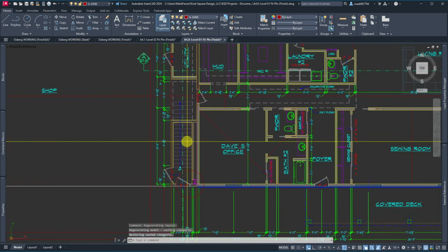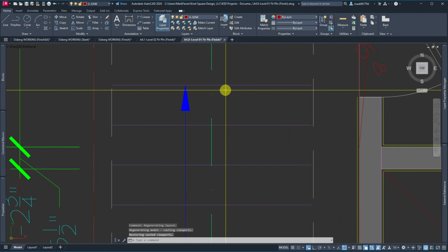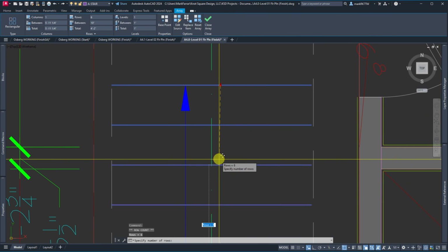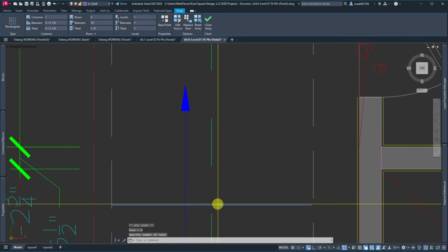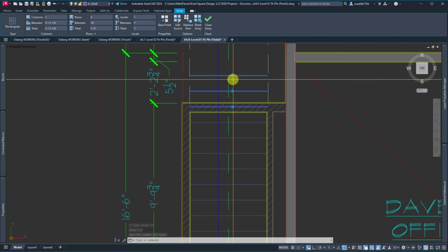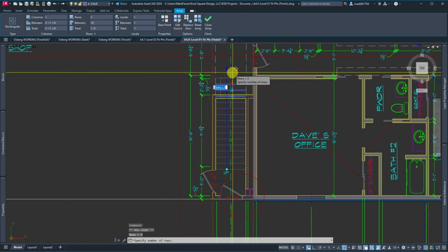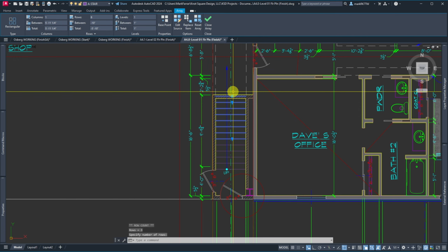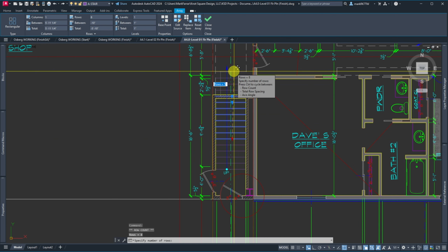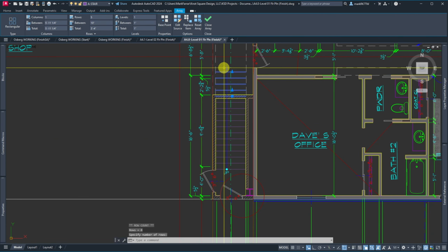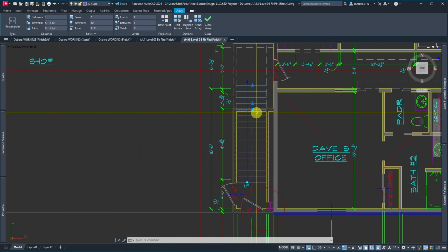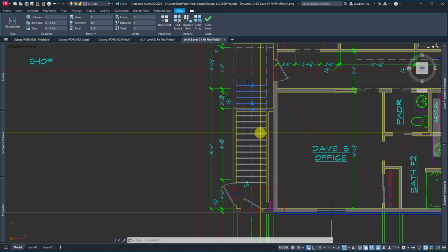Now that that one's ready and says finish, we're going to pull this back, 1, 2, 3, because it's an array. And then, I should excuse myself on that one, this is going to be broken for an upward and a downward. It's snapping to something here. There we go. An upward and a downward, so we'll have two different kinds. We'll have a stair above, which will be a hidden line, and then a stair below, which will not.